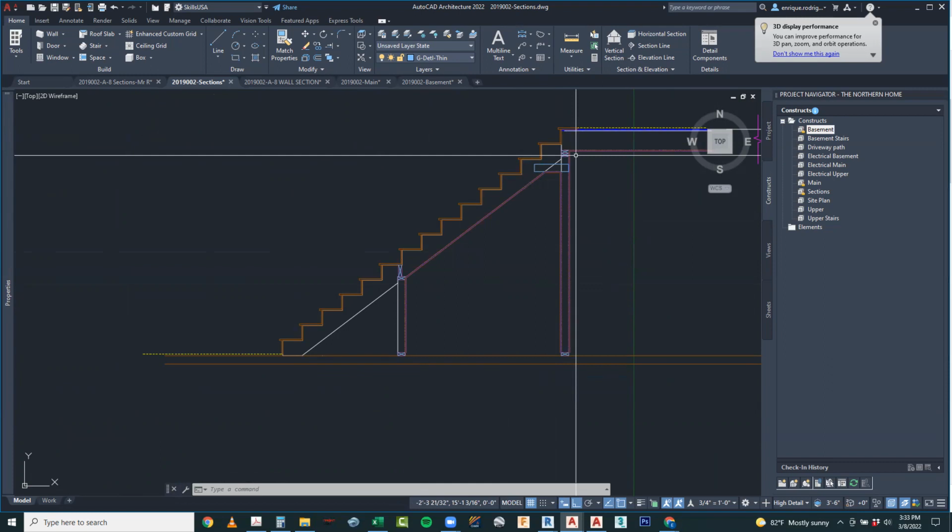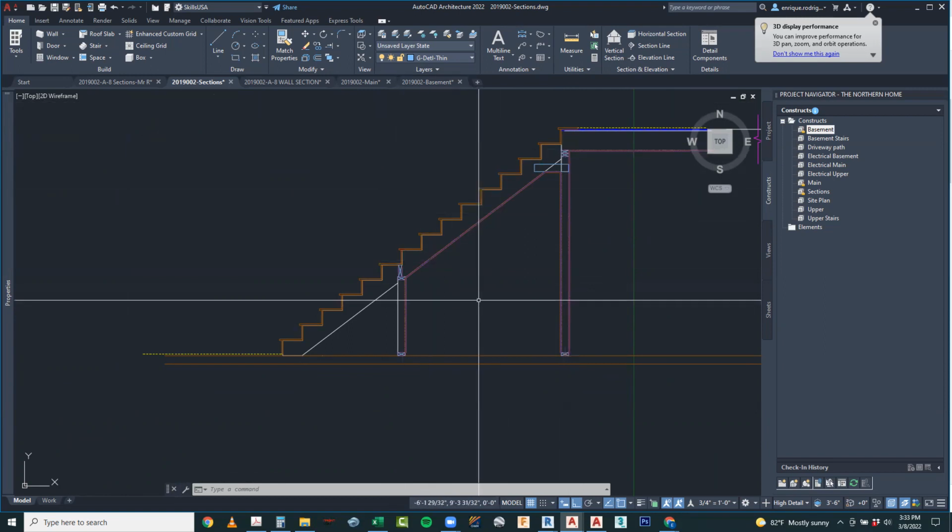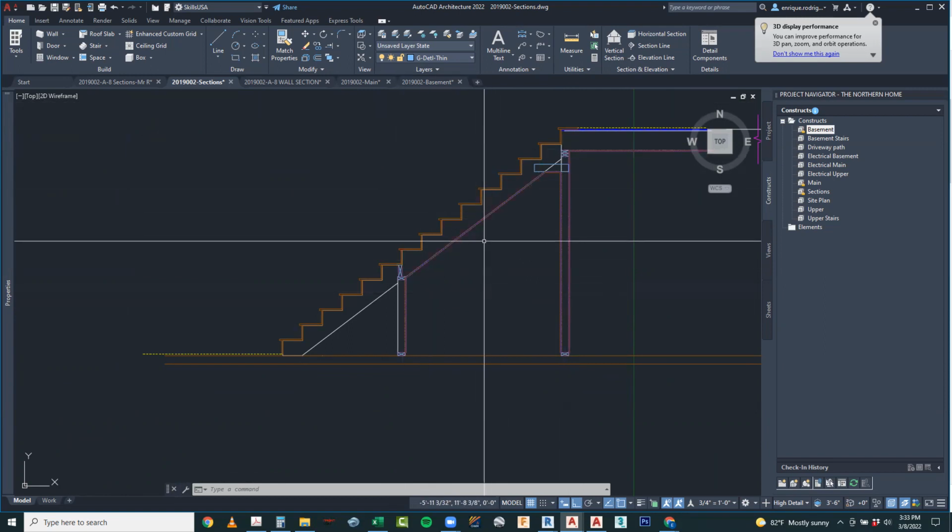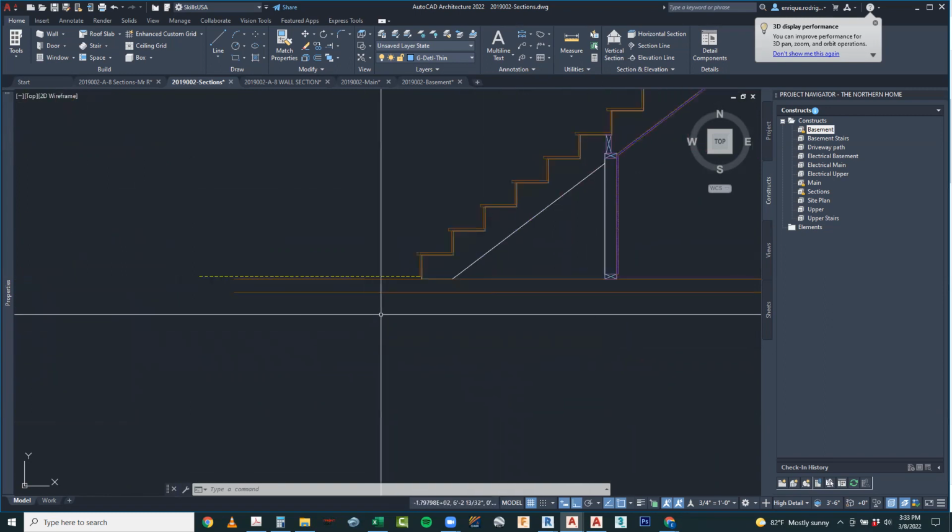So all you need to do is highlight that door, click on it, and change it to how much headroom you think you're going to have. Maybe a 5-foot door, 5 foot tall, maybe less. Once you change it, you then need to update your door schedule. It should update automatically, but it's going to ask you to update it. It'll have a diagonal line across it. All right. So we're pretty well done with this down at the bottom.